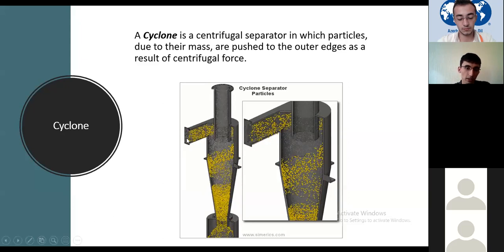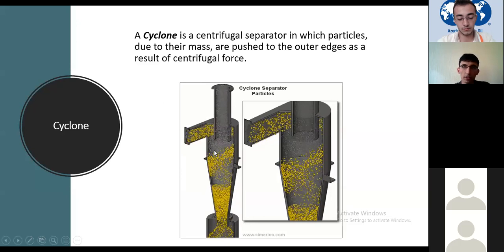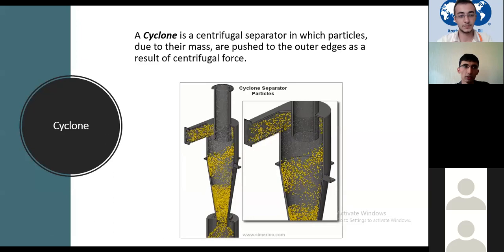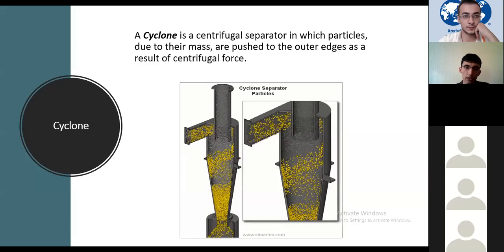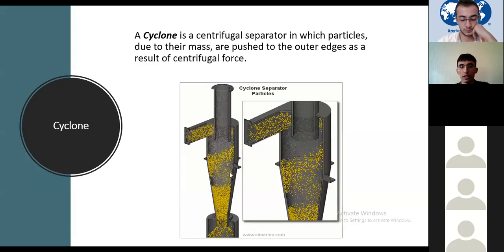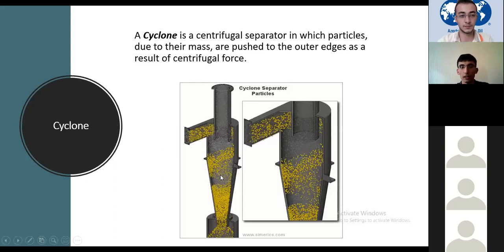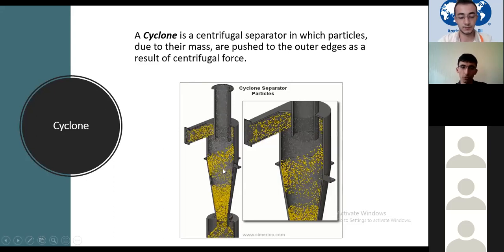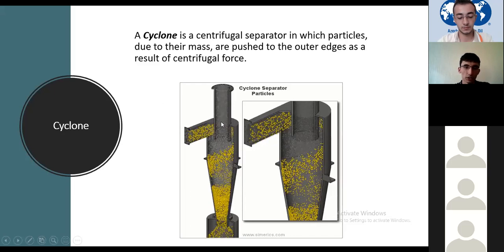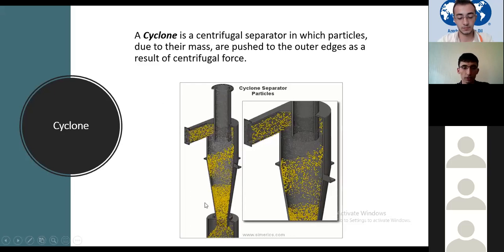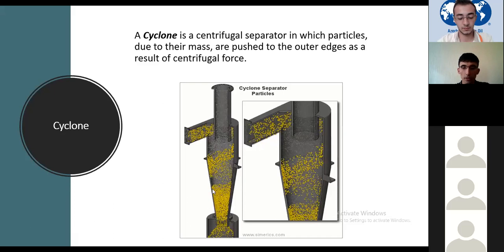When it comes in a radial direction, it flows, and because of their density difference, solids go close to the chamber walls and flow all the way down because of gravity, and then the vortex effect takes action and lets the gas go up all the way through the middle. By using this method, we again separated nitrogen and our solid particles.